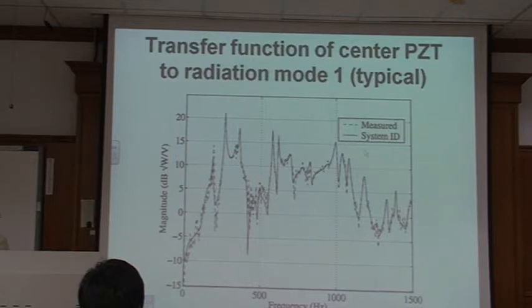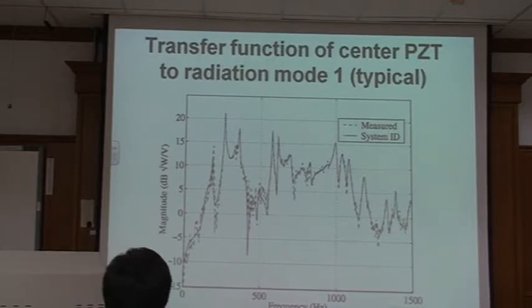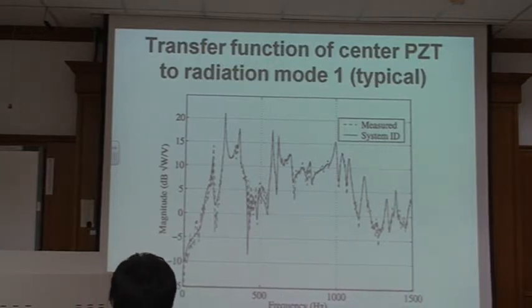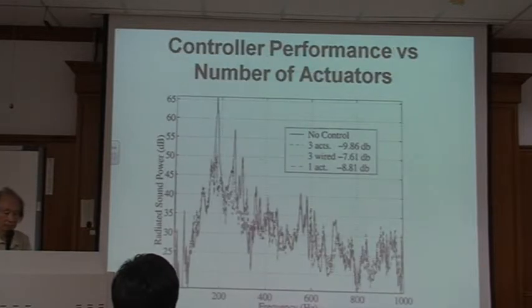So when we do system ID, this is the system ID, and this is the spectrum, input, output, the co-trace functions. So our system ID has to match this, and this has to be accurate, and then this can be good. If this is not accurate, you won't get a good result of this, and you won't get a good result of that. Okay, that's what happened here.